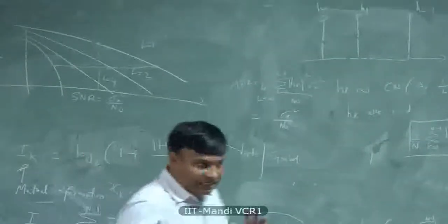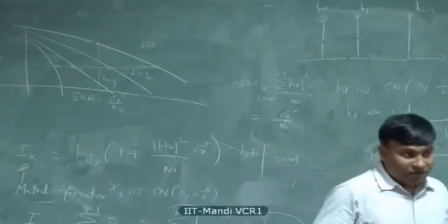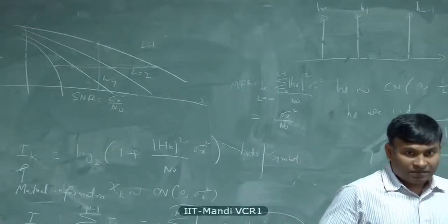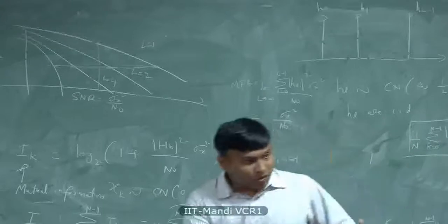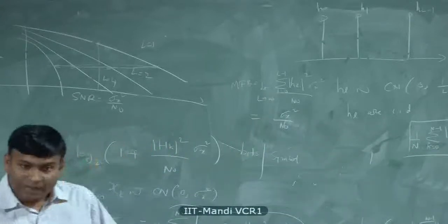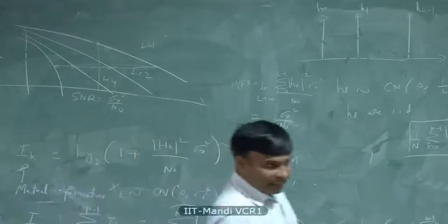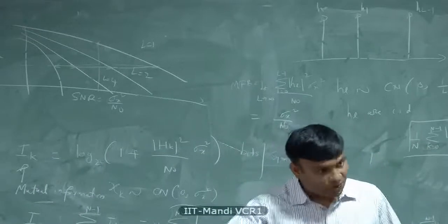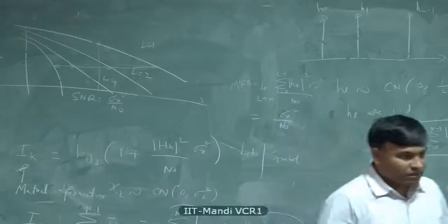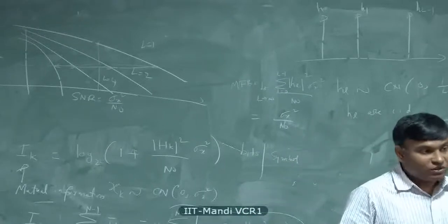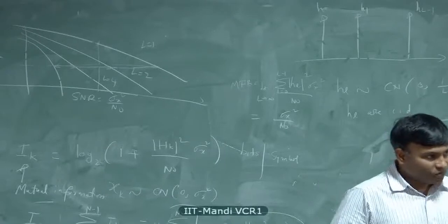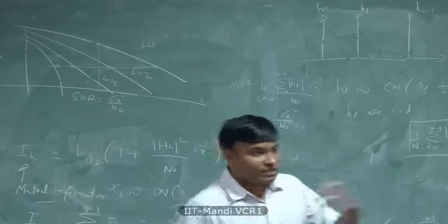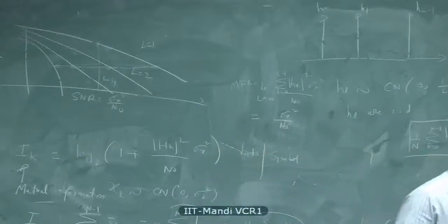So a broadband channel inherently has a lot of multipath delay. Then you may say, well, what about narrowband channels like GSM? Okay. So what is broadband? What is narrowband? Well, it is the bandwidth that dictates whether it is broadband or narrowband. GSM, let's take even an older generation system. There is what is called IS-54 in the US. It's called US TDMA. The bandwidth was 30 kilohertz. Okay, US TDMA. Actually, it's the first American digital cellular standard, IS-54.